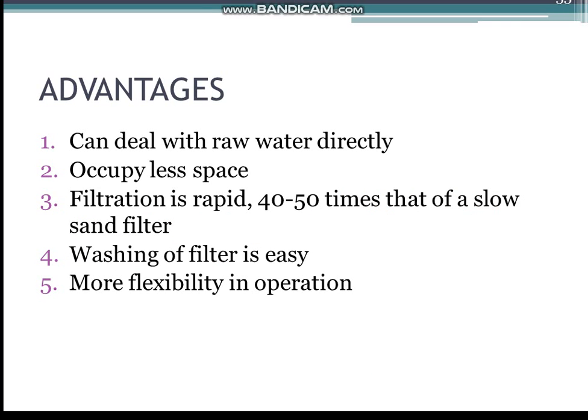What are the advantages of a rapid sand filter over the slow sand filter? First, the rapid sand filter can deal with raw water directly. No preliminary storage is needed. Second, the filter beds occupy less space. Third, filtration is rapid, 40 to 50 times that of a slow sand filter. Fourth, the washing of the filter is easy. Fifth, there is more flexibility in operation.